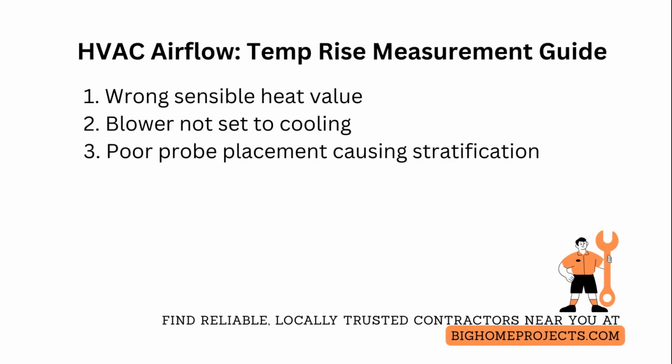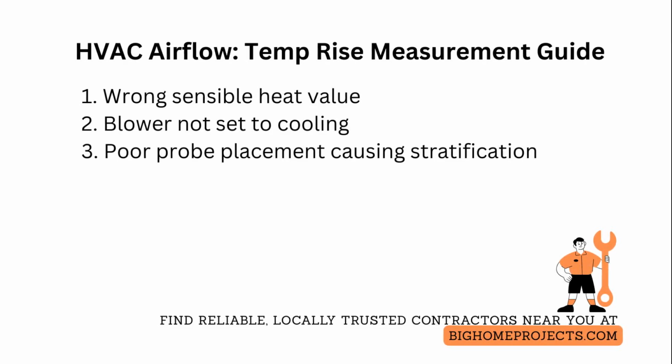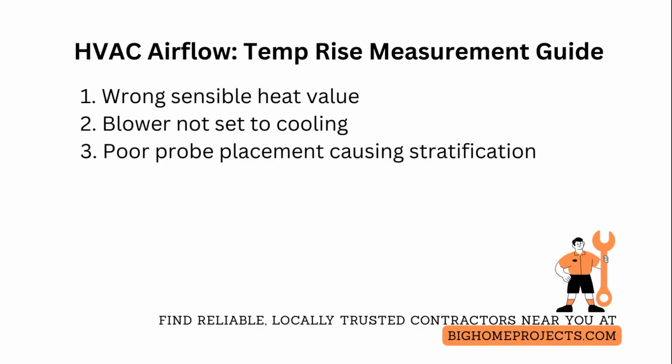One of the most common mistakes is using the wrong sensible heat value for the furnace, which skews the CFM calculation. Fix this by calculating sensible heat from measured output and verified efficiency rather than nameplate input.